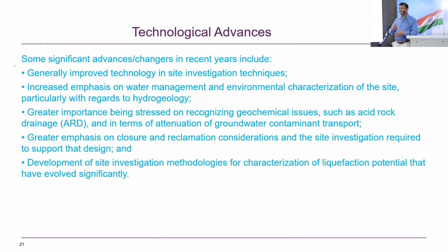But I studied a lot of tailings failures, and I compared what they did in the design with what came out when it failed. When it failed, I found everybody was focusing on the undrained strength, but in the design they used the drained strength.